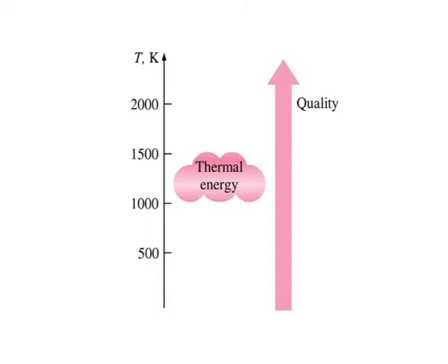Large quantities of solar energy, for example, can be stored in large bodies of water called solar ponds at about 350 Kelvin. This stored energy can be supplied to a heat engine to produce work such as electricity. However, the efficiency of solar pond power plants is very low, under 5%, because of the low quality of the energy stored in the source, and the construction and maintenance costs are relatively high. Therefore, they are not competitive even though the energy supply for such plants is free.